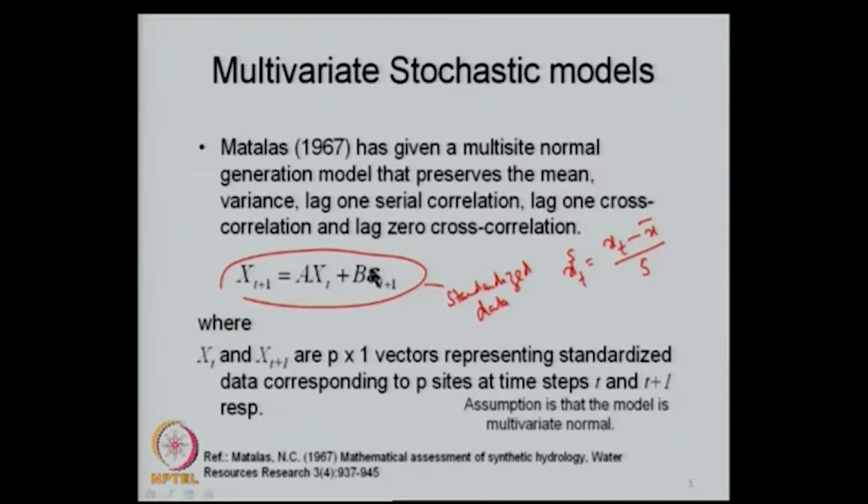So, we use this assumption, and that is why we use these kind of models for large time steps, for example, annual stream flows, seasonal stream flows, etc., where the assumption of these variables being normal is justified. If you use, for example, daily rainfall and such processes which cannot be approximated by normal distribution, then your models will be wrong.